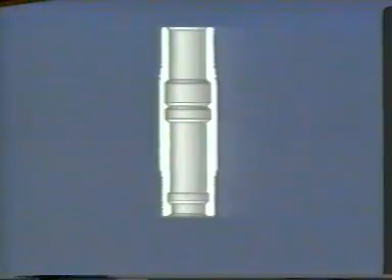For every selective nipple system, there is a compatible no-go nipple that is designed to be used with it. A no-go nipple is a nipple that has a restricted ID as compared to the selective nipple of the same nominal size. Because the nipple is restricted, only one no-go nipple of a given size may be included in the tubing string, and it must be run beneath all selective nipples of the same nominal size for the completion to be compatible. A lock may be run through the upper selective nipples in the tubing until the no-go nipple is reached.